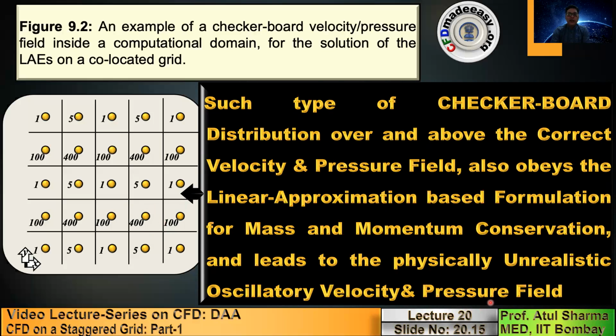So this is called pressure-velocity decoupling, because you end up with an equation for velocities at point P where the value of pressure at capital P is not involved. It so turned out that the mass conservation equation consists of the normal velocities at alternate grid points, not the adjacent grid points, and for momentum conservation, the pressures involved in the equation for the velocities are at alternate grid points.